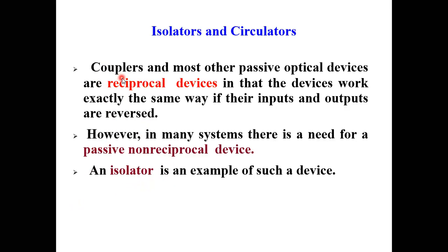So please mark this thing. Couplers and isolators are both passive devices. Coupler is a reciprocal device. Again repeating, reciprocal means I can change the input and output terminal. And isolator is a non-reciprocal device, which means whichever is input, that has to be the input.